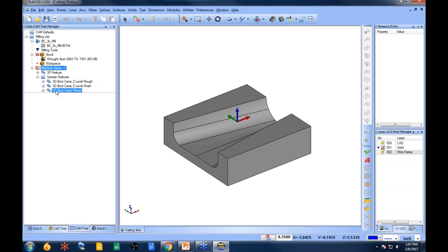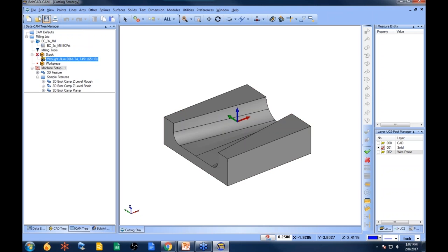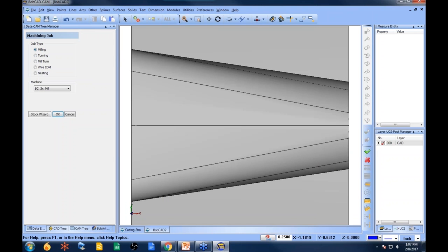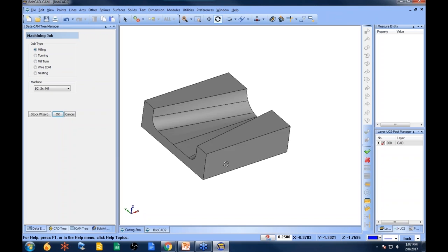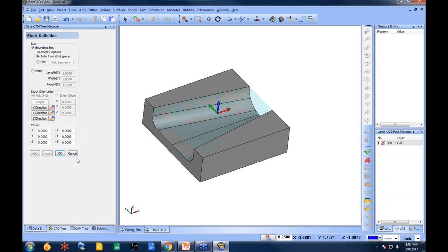So, when you're starting fresh, like when we're starting new, and I'm only going to go through this one time in this webinar because I want to spend more time focusing on the toolpaths, right? So you have a new part, whether it's at the world or not, you got to create a job. The job is where all your toolpath is generated, right? So we're going to run the stock wizard. We're going to next through the workpiece. We're going to use rectangular stock. There are other stock types, but in this example, we're choosing rectangular.